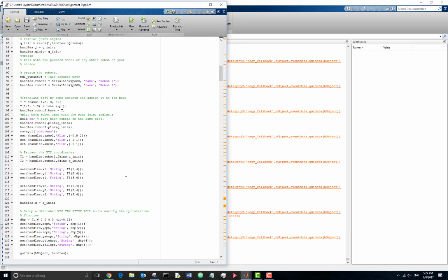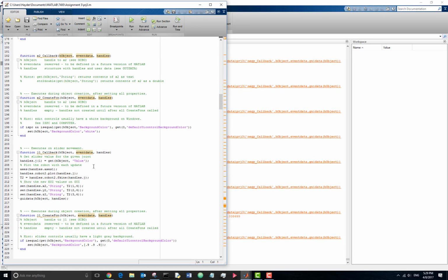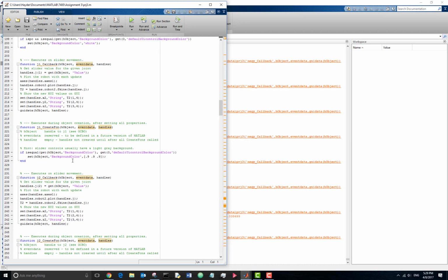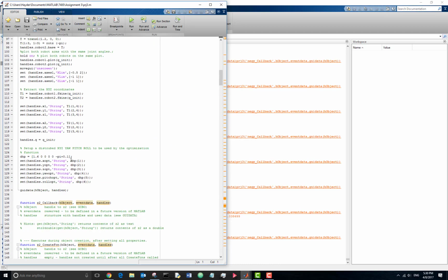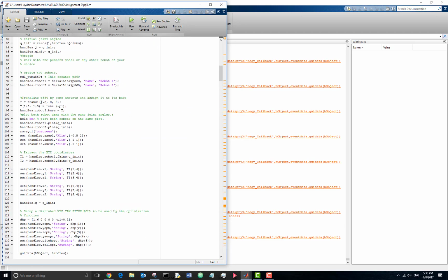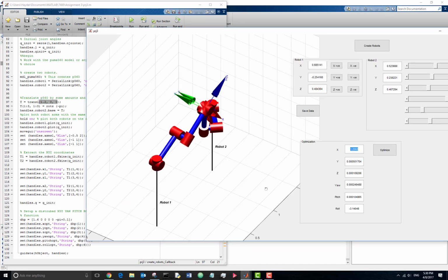So as you can see in my code, the transformation that I have created is this, which is a translation 1.200. As you can see here, we have 1.2002, which is very close. And then these are 0. They are very, very small values until the rotation about the z-axis, which is the roll, is minus 3.14, which is basically minus pi.